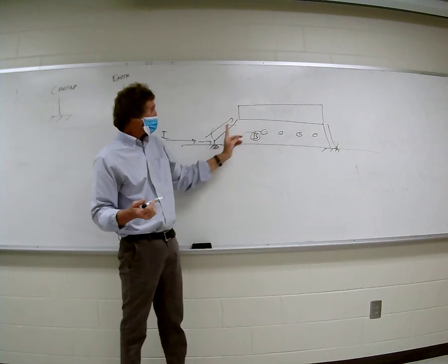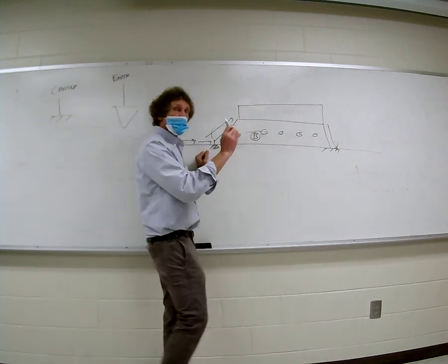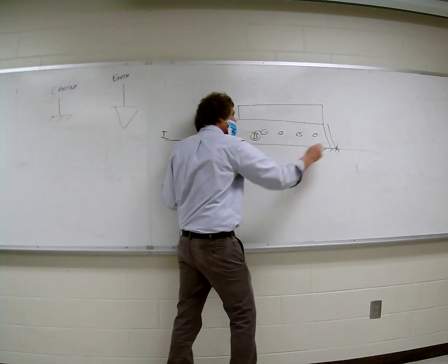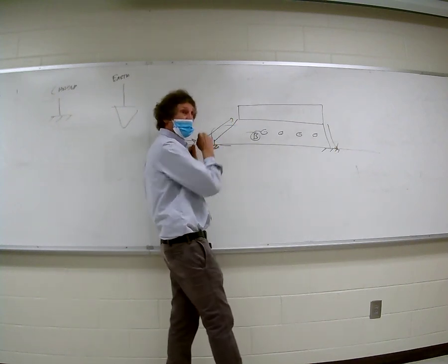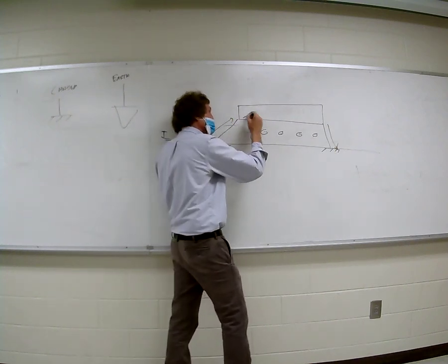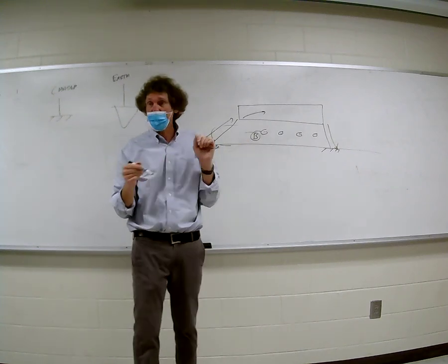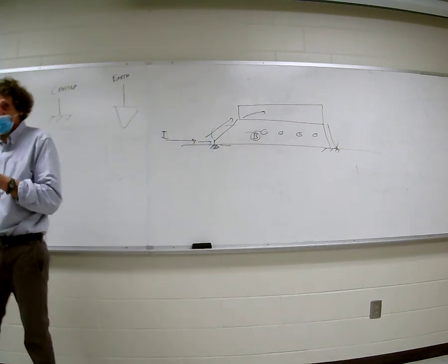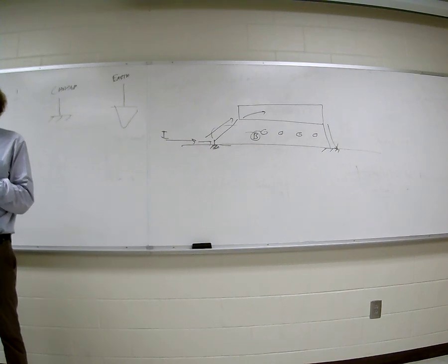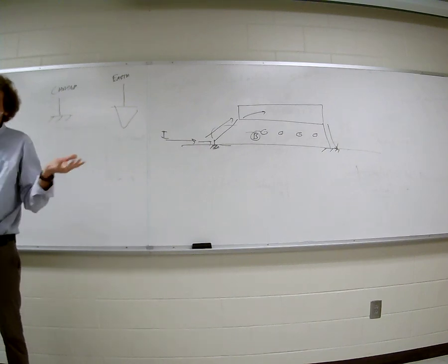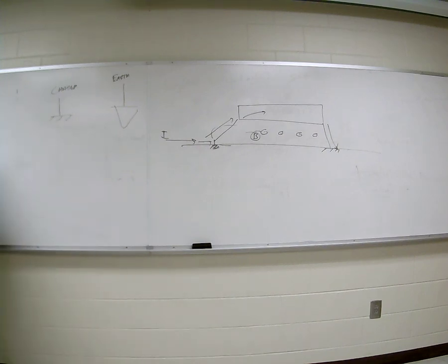So if you ground anything at 2 points, you open yourself up to this thing acting as a single coil and inducing EMF in it. And these things can be serious if you have a high power current or if lightning hits nearby. Lightning's really the bad one. Follow me? So the moral of the story is ground at 1 point, and you won't have any problems with chassis grounds. If you go from any kind of a unit to another ground, either from chassis to earth or from signal to chassis, go through one path only.